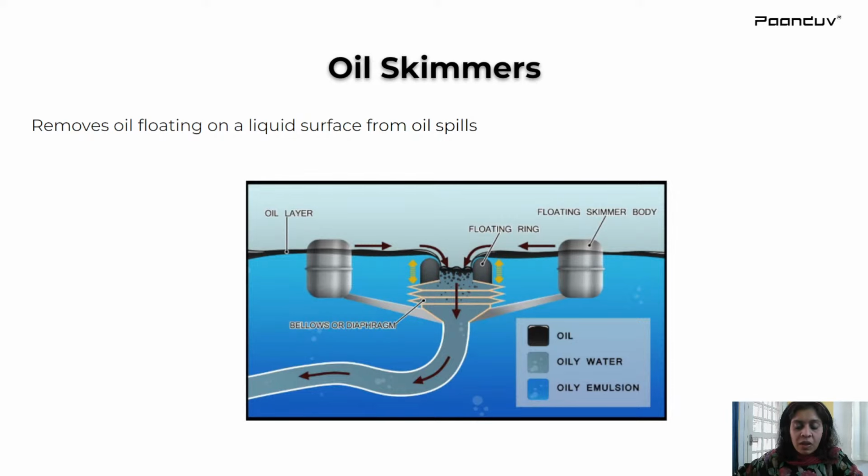An oil skimmer is a floating device which sucks the oil and air at the surface. It goes to the external circuit where you have the scraper. You scrape the conveyor belt, and through this rotary motion the oil is eliminated and the water comes back to the source.